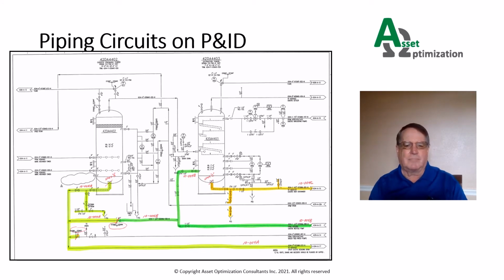color-coded in the unit. The color-coded circuitized P&IDs can then be used as a go-by for creating piping inspection ISOs in the field, as well as for piping circuit data collection.